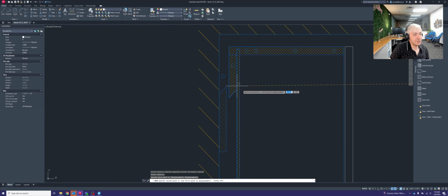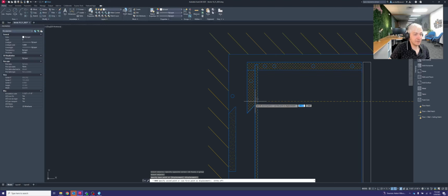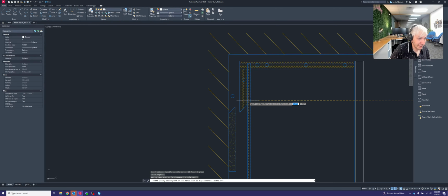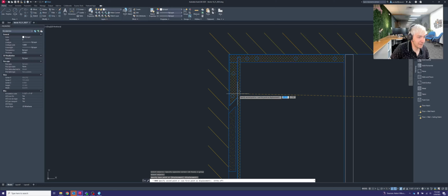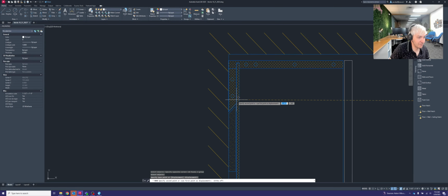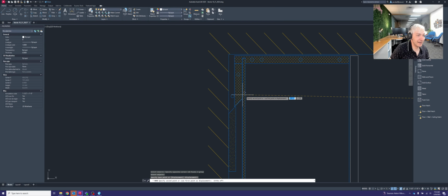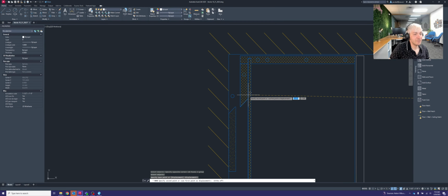So what I need to do is have what's called lift-off space. When I go to install an upper cabinet, I actually need to lift it up approximately 3/4 of an inch, slide it back, and then drop it down like this, which will lock that cabinet in place, and then it's not going to go anywhere. But because of the angle on the cleat, I do need to be able to lift this up and move it forward or back to be able to install it.